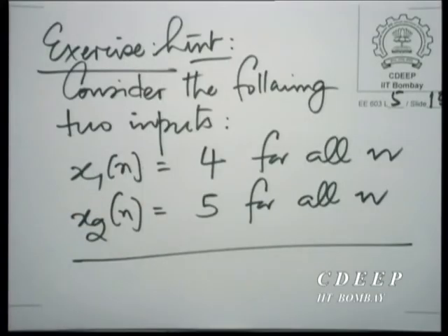So, we wanted to prove the system is not linear. Now, there one counter example is enough. So, once I take this troublesome input and I prove that the system does not satisfy linearity or superposition for this, it is enough for me to conclude the system is non-linear. But the reverse is not true. If I take some examples and I notice superposition is obeyed in those examples, it is not adequate to conclude the system is linear, and in a minute you will understand why.